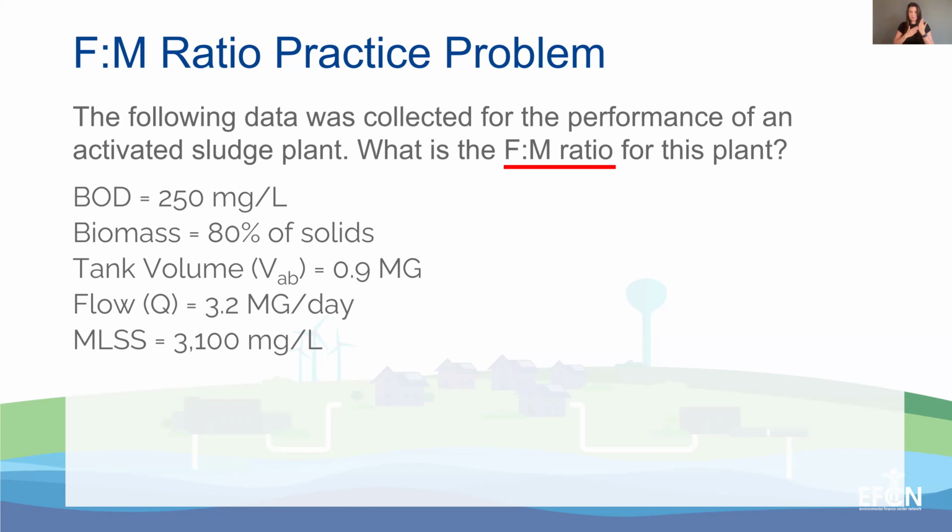So I'll give you guys about a minute to do this one real quick. We'll give it another about 10 seconds. Just a quick hint for anyone trying to figure out where to go. If you remember, it's 80% of our solids, and our MLSS represents our solids. So you take 80% of that to calculate the MLVSS.